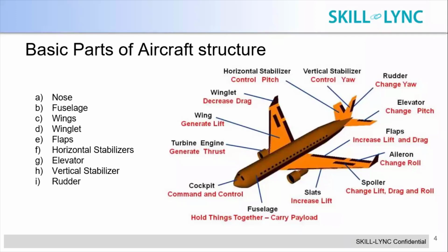So it stabilizes the flight of the plane, right? Even the horizontal and vertical stabilizers have their own control surfaces, which also help the plane in maneuvering, right? And the vertical stabilizer has got a rudder, which helps the plane to maneuver sidewards,